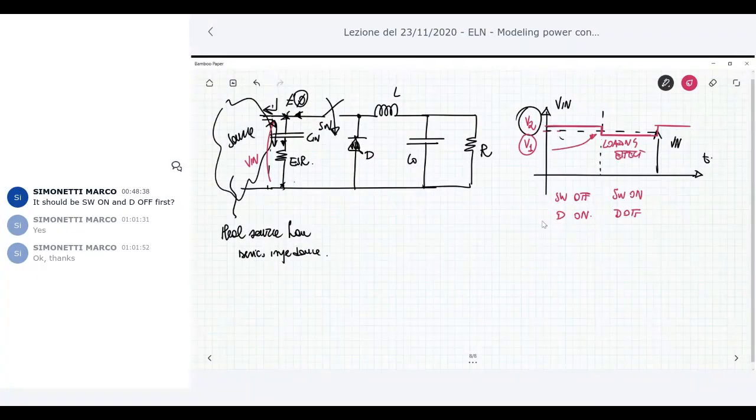There is a load here represented by the switch, which is closed, and there is a current here which now has this direction. This current draws some partial current away from the input capacitor, so it absorbs some current and avoids an increase of the input voltage. So the input voltage, due to the presence of ESR, is not exactly constant as we think in our steady state analysis.